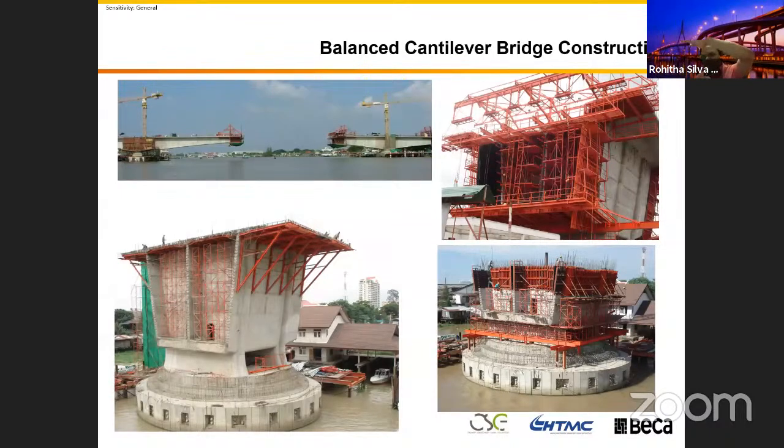cube over 3EI, right? So when your L is larger, it just keeps going down. So when you are building a bridge, we have to camber it out, because you can't have a road surface go up and down like when you are driving a car. So you have to build your bridge up like that. This calculation, we call the camber diagram, is all theoretical, what people predict.